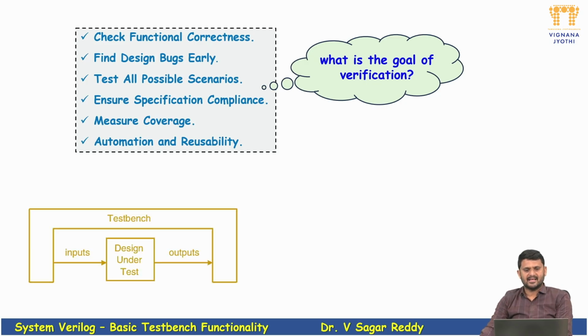A test bench is a virtual testing environment created in System Verilog or Verilog to verify, validate, and ensure that the DUT behaves correctly under all possible scenarios before it's synthesized or implemented on hardware. Reusability is one more important aspect here. We can reuse the same test bench for multiple designs and also for configurations. Why does this matter in the real world? In the semiconductor industry, verification consumes nearly 70% of the total design effort. That's not a coincidence. That's a reflection of how critical it is.